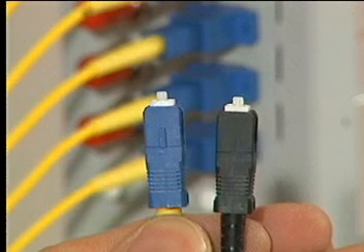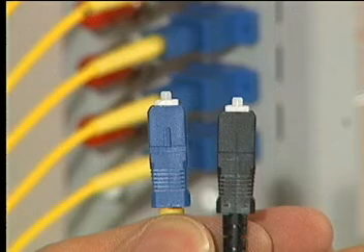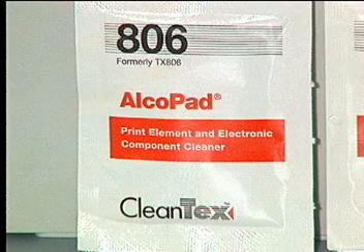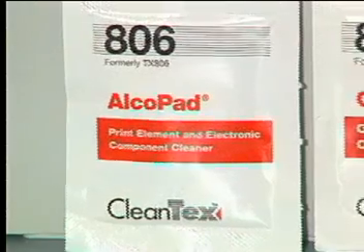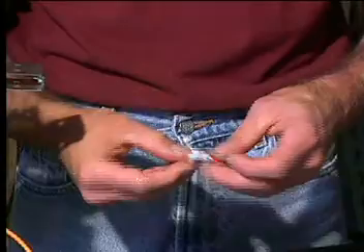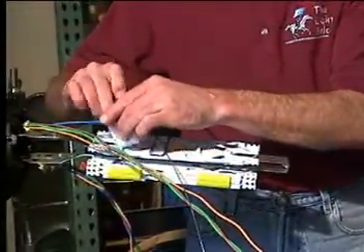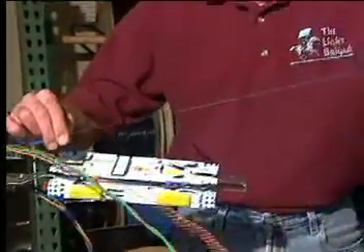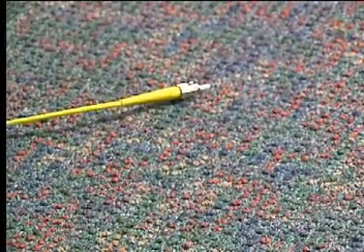In the past, cleaning connector ferrules was usually done using pads pre-saturated with isopropyl alcohol. Two types of pad are commonly used in fiber optics work. Alcohol-soaked pads are soft and fully saturated, while optic pads are a fine lens paper only slightly moistened with alcohol. Alcohol pads find extensive use in removing cable gel and plastic residue when preparing cables and stripping fibers. Optic pads are more suitable for connector cleaning than alcohol-soaked pads unless a large amount of dirt must be removed, as in the case of a connector dropped on the floor.